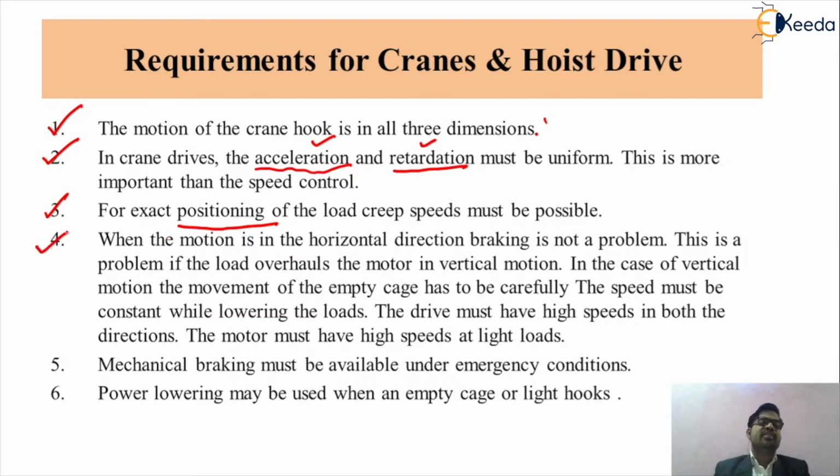Then the next and very important requirement is that when the motion is in the horizontal direction, braking is not a problem, but when the direction is vertical, the braking will play a very vital role, because as we have seen, while an object is moving in the downward direction, due to the force of gravity it will create some damage. So friends, while we are selecting cranes and hoists for a particular application, the speed must be constant while lowering the loads. This is a very important requirement for cranes and hoist drives.